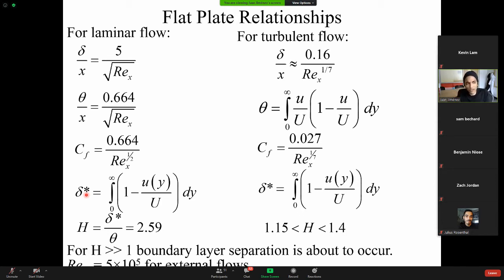And in general, why is that number used? Many times, for people who study boundary layers, measuring the boundary layer is actually very difficult, because when you have an actual physical probe, getting close to the wall and measuring what's happening at the wall is very hard. That's the main reason they use this, because this value is really large far away from the wall and very small near the wall.